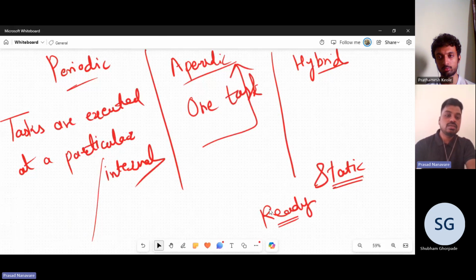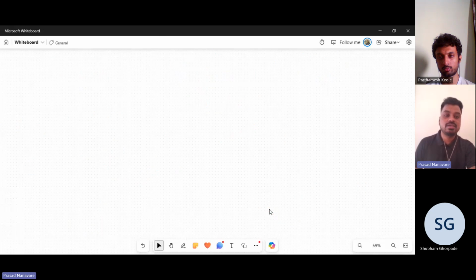ओके, द टास्क की प्रियोरिटी होती है, अगेन स्टैटिक प्रियोरिटी, डायनामिक, ये दोनों, ये मैं लिख भी नहीं रहा हूँ इसको। वेरी सिंपल, static priorities you define earlier, dynamic priority can change during the execution। Okay, based on the task deadlines। Okay, so priority inversion क्या होता है, a lower priority task can block the higher priority task if both share the same resources। Okay, अगर wait let me write it।